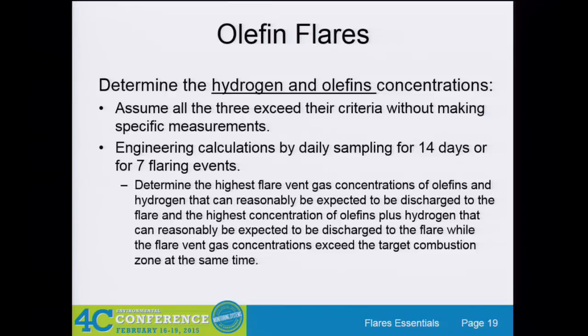That causes some problems because the hydrogen leaks out of a Tedlar bag, so that's not a good thing. There have been alternatives proposed to the EPA and accepted which allow Summa canisters for getting those samples. But if you just go straight to the method, you won't even know that these alternatives exist. You have to go to a specific website where they're all posted. And that's what I'll be talking about tomorrow as part of my presentation.